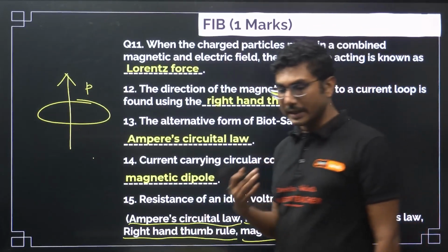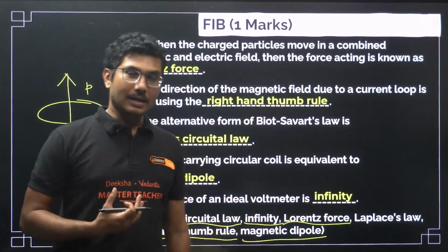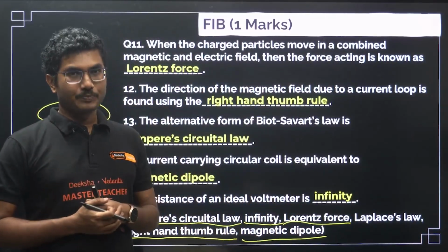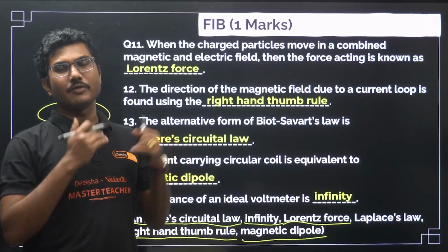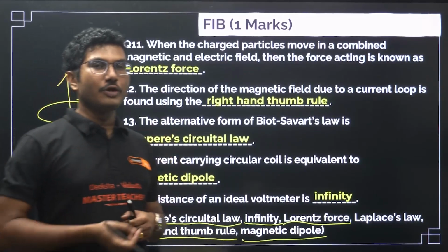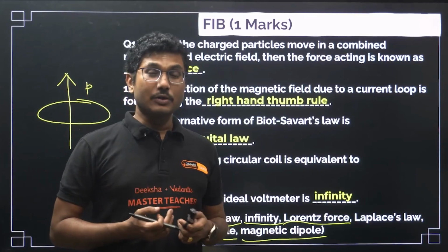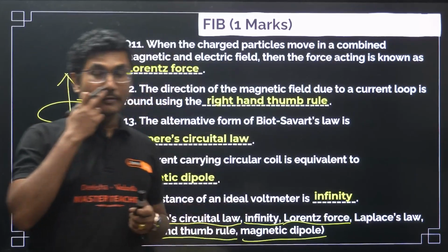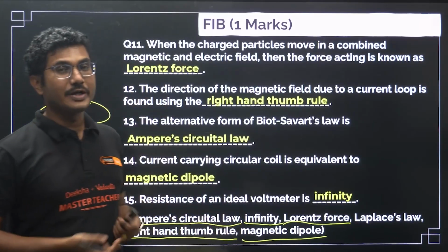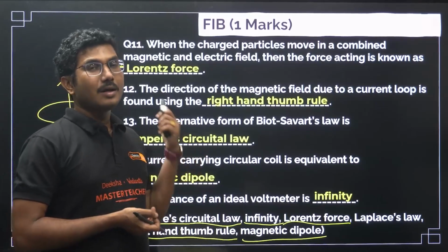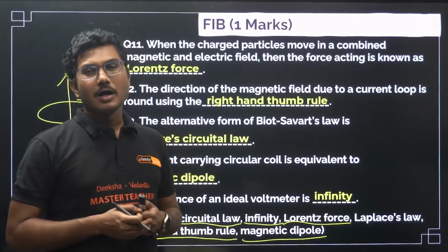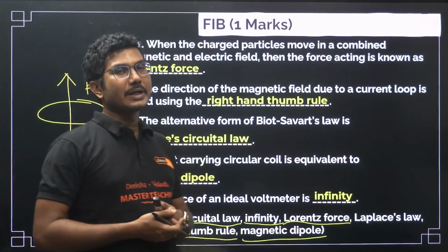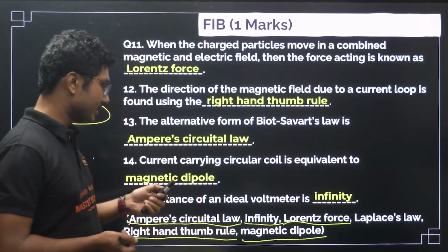If you are connecting something in parallel to measure voltage, ideally it should not draw any current from the circuit, so that the actual voltage is accessible to you. That is why an ideal voltmeter should have very high resistance, equivalent to infinity.